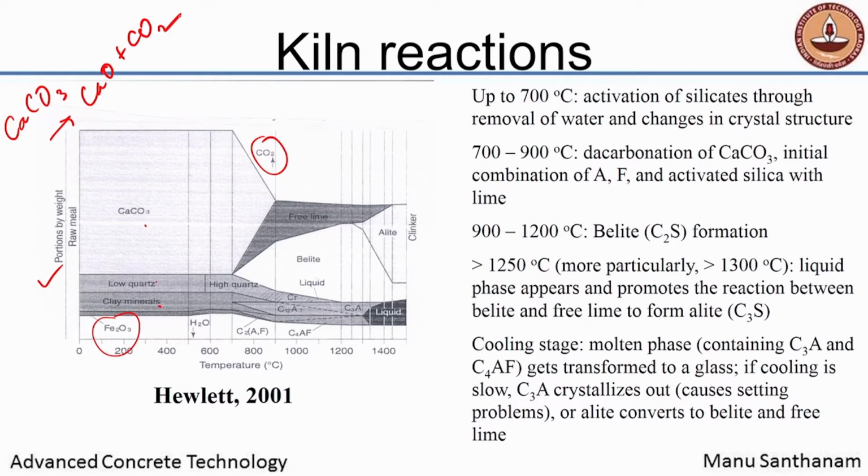Now, if you look at the molecular masses, CaCO3 has a molecular mass of 100, CO2 is 44 and CaO is 56. So, for every 100 kilograms of CaCO3 that is coming into this process, 44 kilograms of CO2 is getting lost. It is a gas, so we do not have mass, we have the mass equivalent of CO2 getting lost, about 44 kilograms. Okay. So, approximately close to half of this limestone is coming out as CO2, definitely less than half, but close to half.